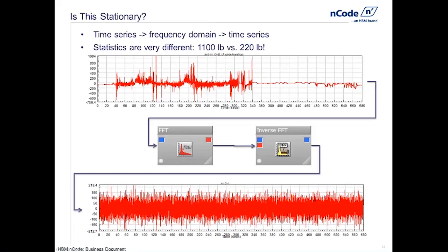Now, some of you may say, hey, wait a minute. Actually, in the fast Fourier transform, we have an option. We can have the frequency spectrum y-axis be scaled as an average amplitude or as a peak amplitude. Okay, so we can look at an average or peak amplitude. I've said average a lot today. True, peak does exist. A peak amplitude would say that we'd pick up peaks that way, but that would say in the frequency domain that peaks always happen,